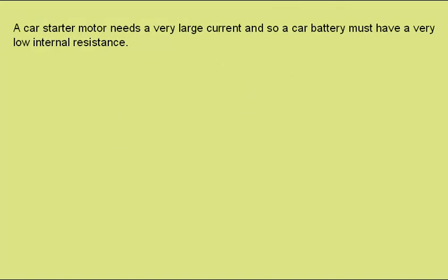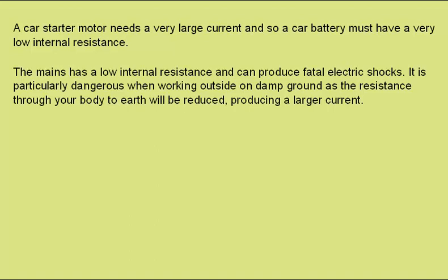A car starter motor needs a very large current, and so a car battery must have a very low internal resistance to allow this large current to flow. The mains has a very low internal resistance and can produce fatal electric shocks.